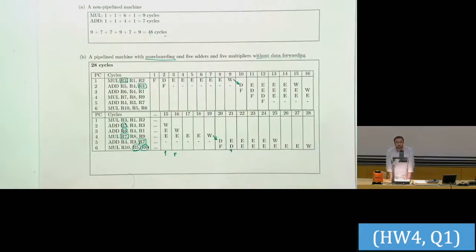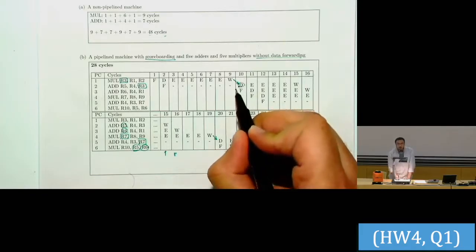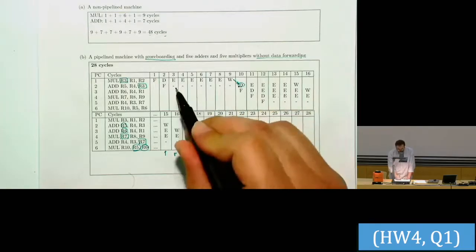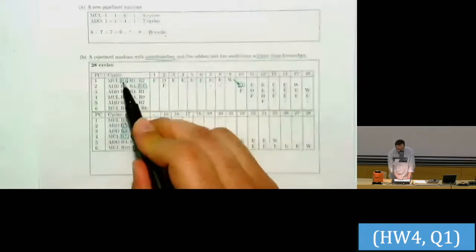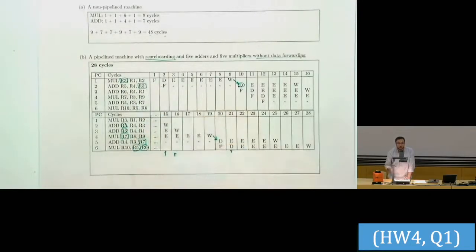Yes? Why can't you decode the following instruction while it is executing the first one? Why can I decode the second instruction that is dependent? So this decode goes to where in your question? The third column here? But you need to finish the execution to understand what the value of R3 is, to be able to get R3 and put it to the...